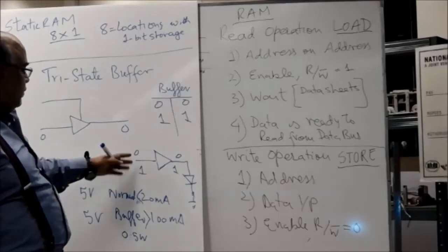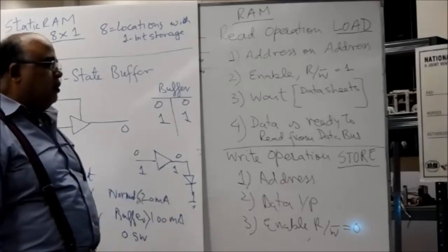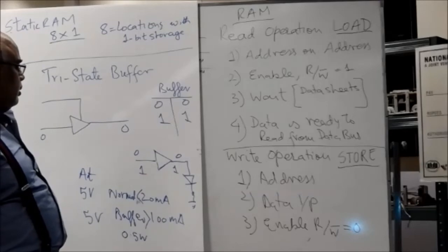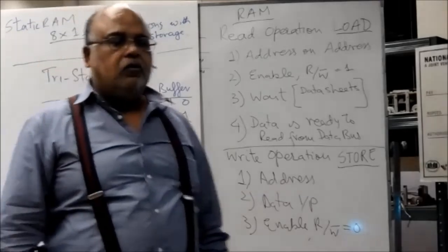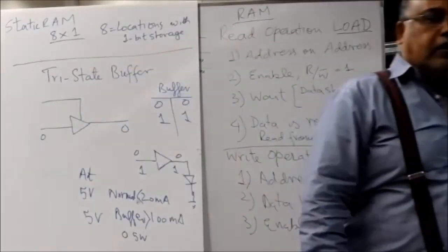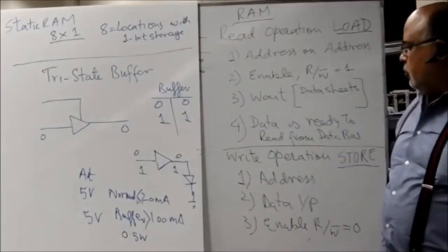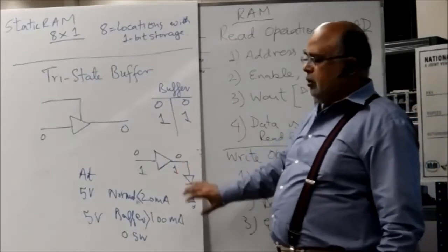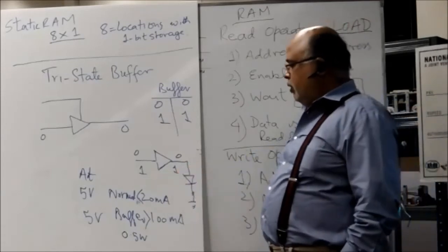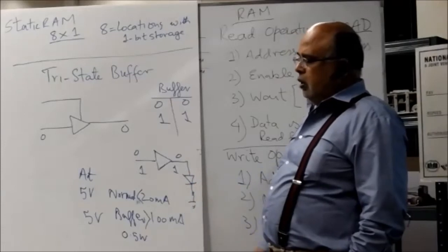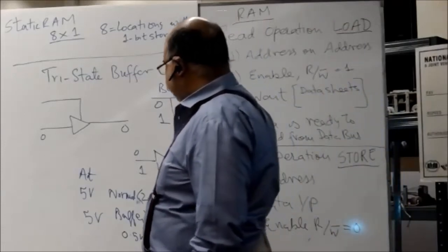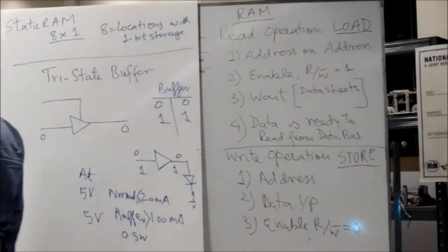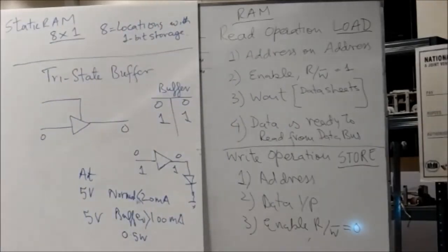Many buffers have direct LED connections that you can make with them, so that you don't have to have a separate LED driver. Some ICs come with a direct buffer at the output, so that you don't have to use a special circuit for LED driving. Or you can use it to directly turn on a relay or something like that. So that's the job of the buffer.